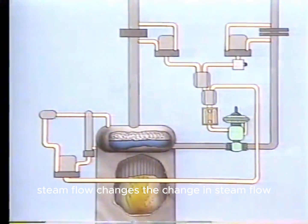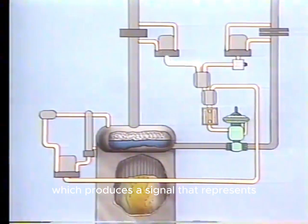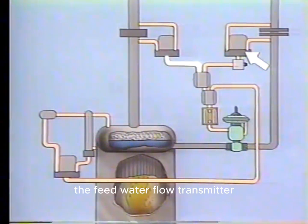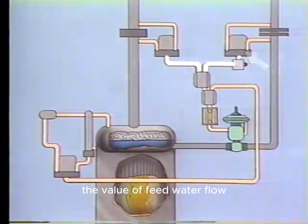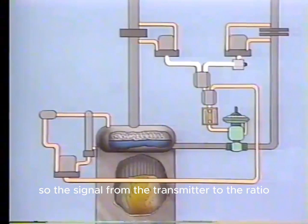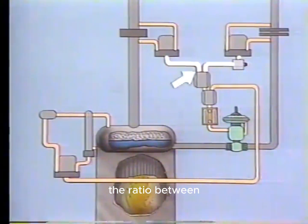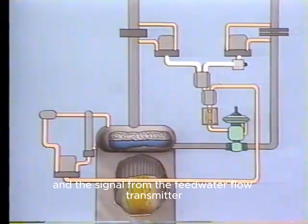The change in steam flow is measured by the steam flow transmitter, which produces a signal that represents the new steam flow rate. This signal is sent to the ratio controller. The feed water flow transmitter produces a signal that represents the value of feed water flow. Up to this time, feed water flow has not changed, so the signal from the transmitter to the ratio controller has not changed. The ratio controller computes the ratio between the signal from the steam flow transmitter and the signal from the feed water flow transmitter.